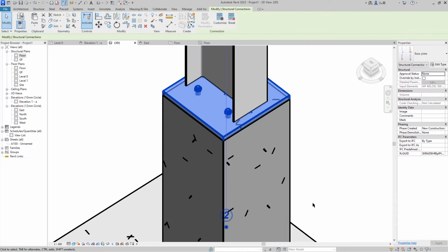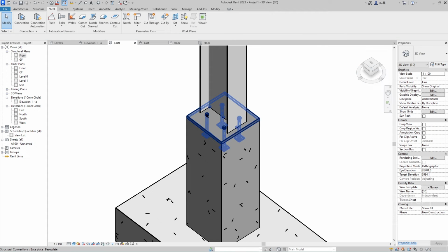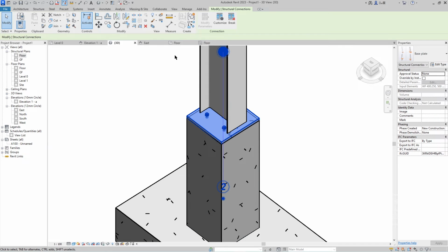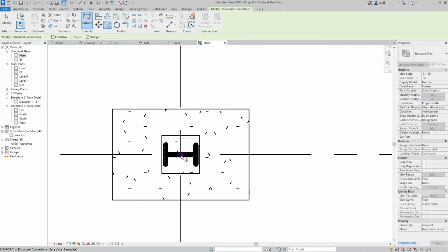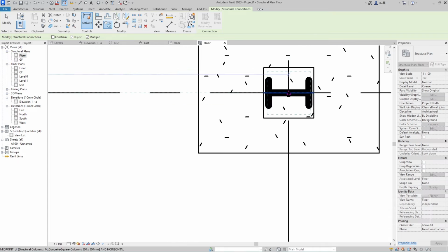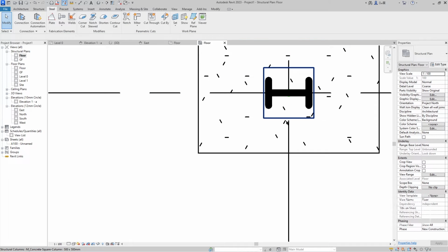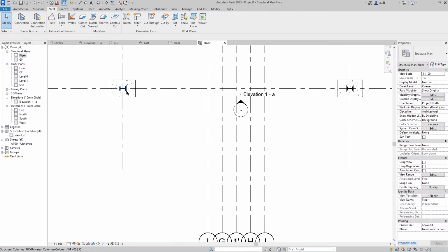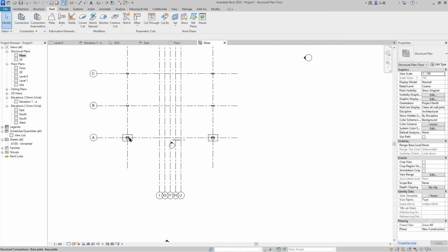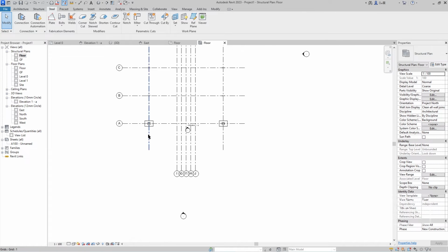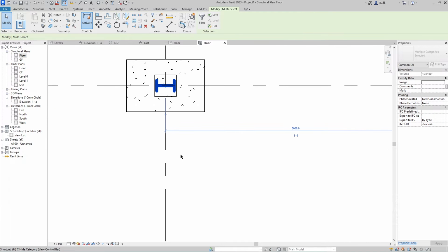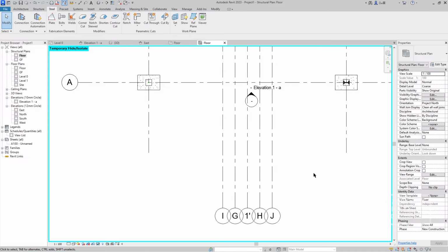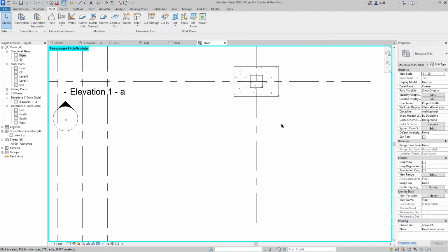It's okay. So all we need is also just copying the connection to be more efficient in time. Go to the floor structural plans view and then typing CO, take the center point, go to here. Here we go. We're just copying everything of the connection between the concrete and the beam. So after that we just need to copy it through grid A into the A grid. So let me first hide the steel frame by typing HH, and after that also within this one, just wait a minute, temporary hide.